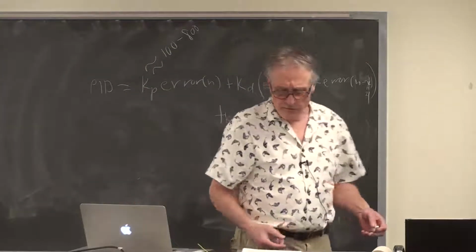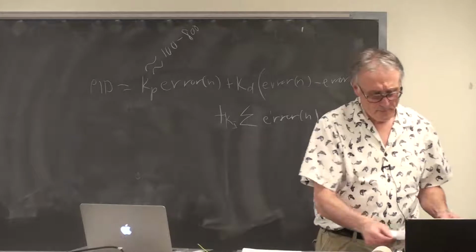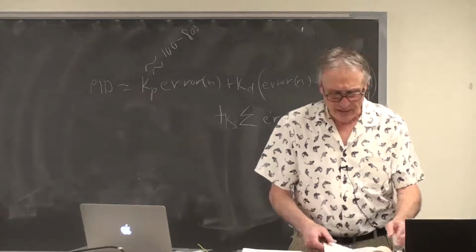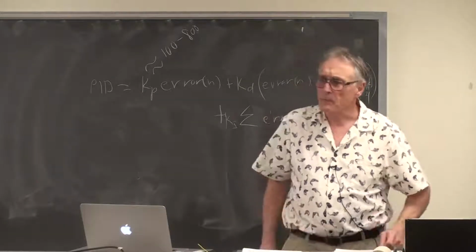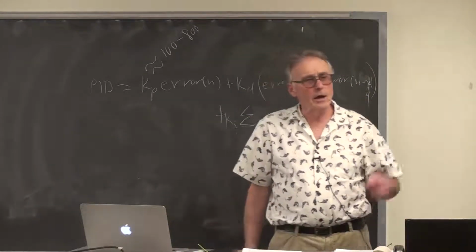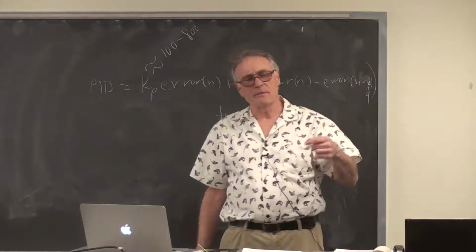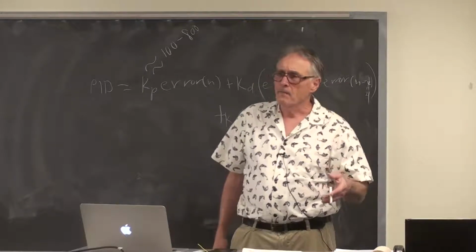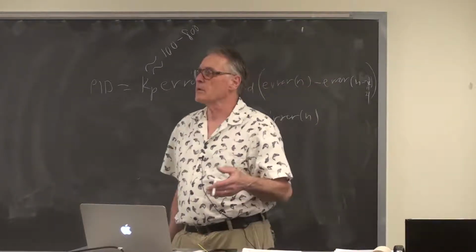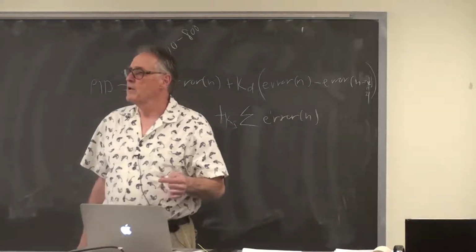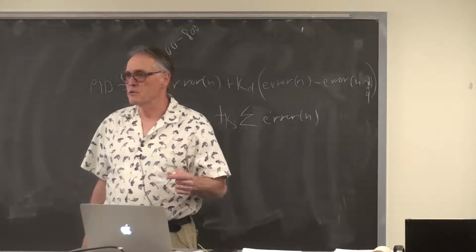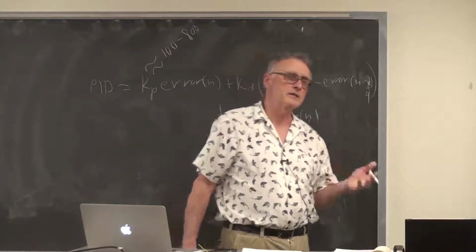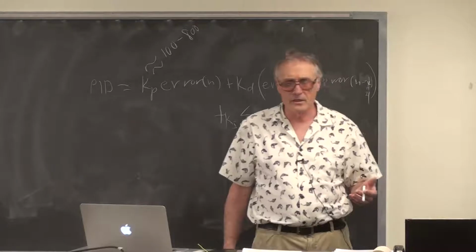What about the first derivative? Now we have to guess how fast that thing can turn. So I'm guessing, I think that this is about right. I mean, the natural period of this pendulum is around a second, but that motor I think will generate about 3 G's acceleration or so. So you figure that the time constant is going to be something like 300 milliseconds or so.